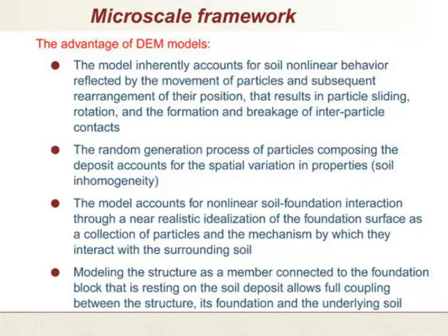Also, the random generation process of particles composing the soil deposit produces a system that has a spatial variation in properties. So inherently, it accounts for soil inhomogeneity. The model accounts for nonlinear soil foundation interaction through a near-realistic idealization of the surface of the footing interacting with the particles. So there is no need for special interface elements. That's really what it means.